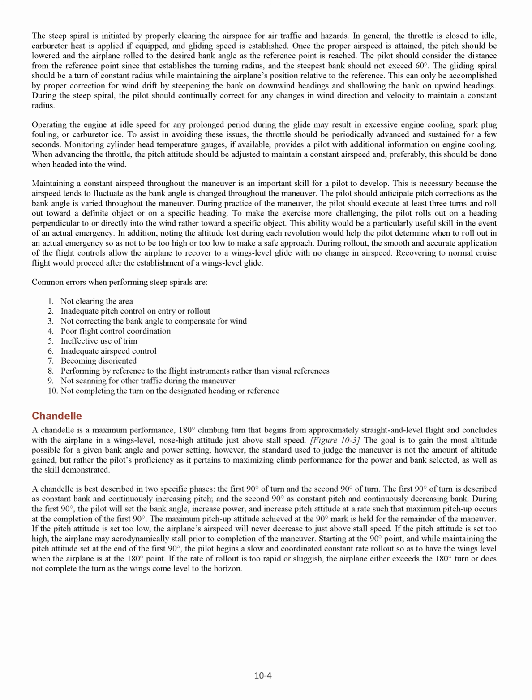Operating the engine at idle speed for any prolonged period during the glide may result in excessive engine cooling, spark plug fouling, or carburetor ice. To assist in avoiding these issues, the throttle should be periodically advanced and sustained for a few seconds. Monitoring cylinder head temperature gauges, if available, provides a pilot with additional information on engine cooling.